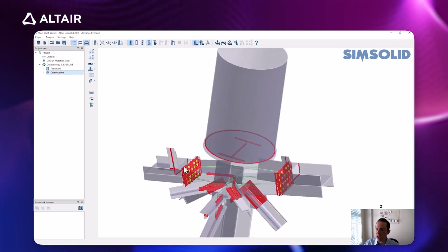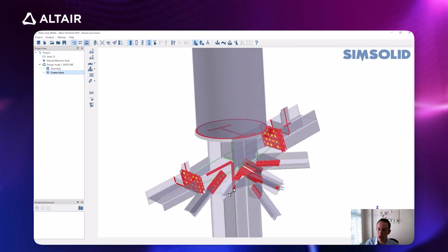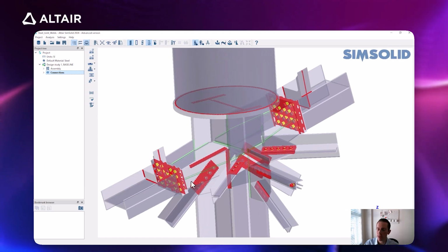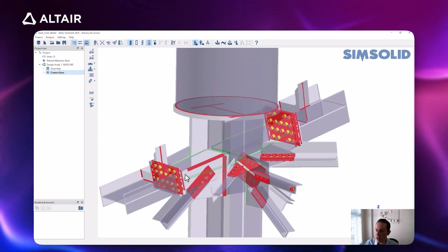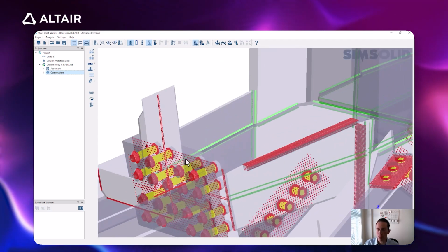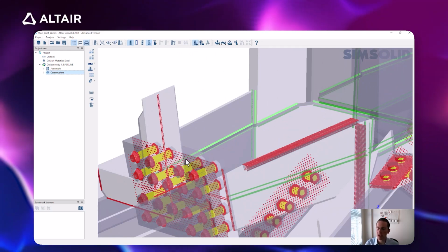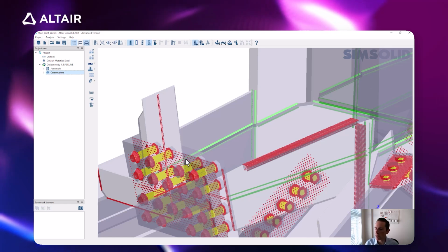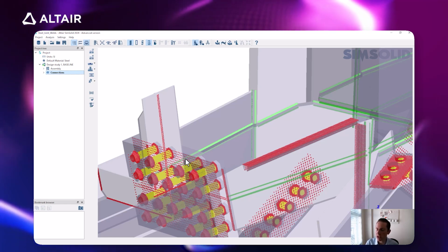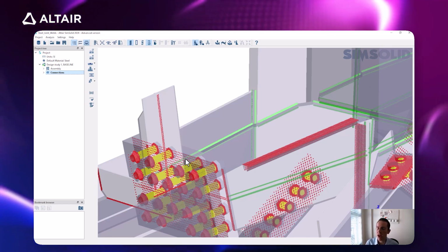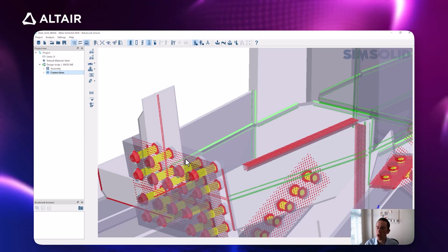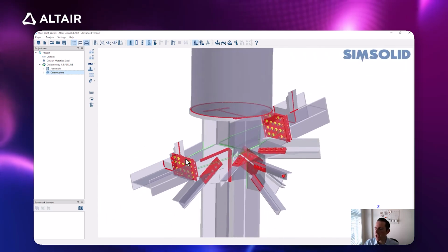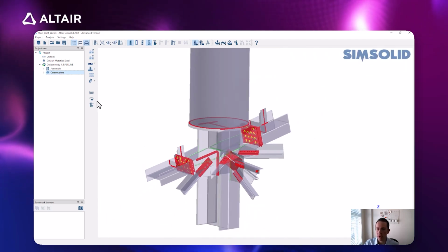And we've got all these red and yellow shades all over our model. So what this has done for us is it's generated all these different connections based off of the parameters we set up. The red indicating the presence of bonded connections, meaning that those parts are sharing all 6 degrees of freedom, and the yellow indicating sliding connections, where it's automatically identified the bolts in our model in this case, and it's applying a sliding connection where it's going to remove that rotational constraint from those connections there. And we can modify this manually if we want to, but I'm not going to worry about doing that right now.